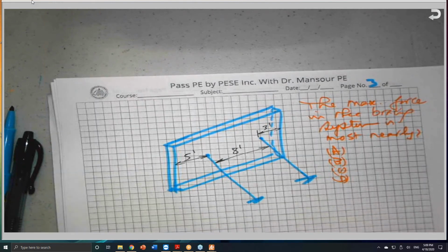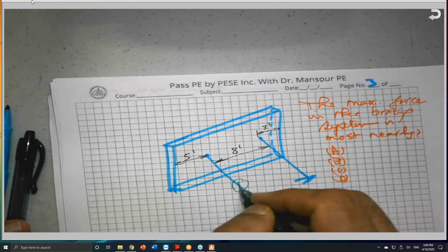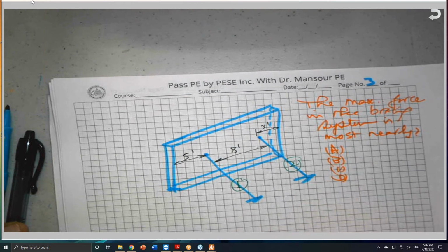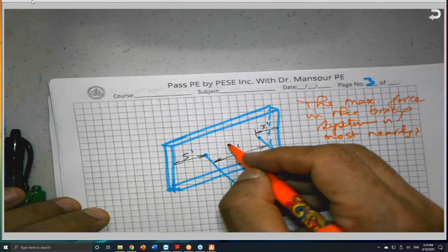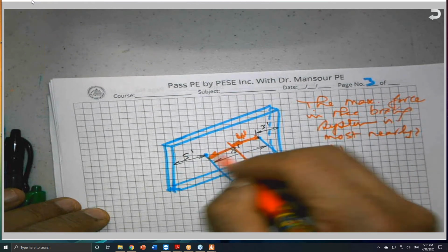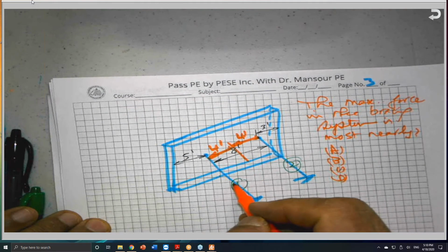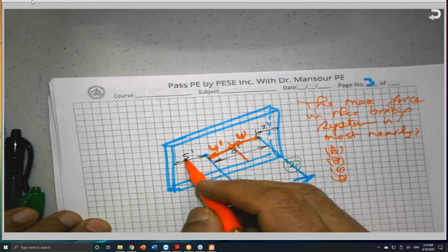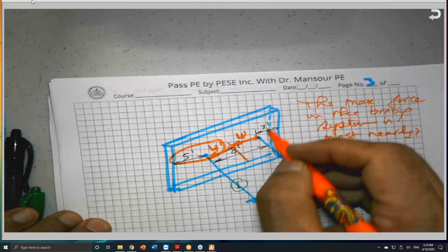In this case, we do have one brace, which is brace number 1, and this is brace number 2. The tributary width is still the same. So I will come here and I say this is 4 feet from each side, 4 feet and 4 feet. So the tributary width of this became 4 and 5 is 9. And this is just only 7 feet.